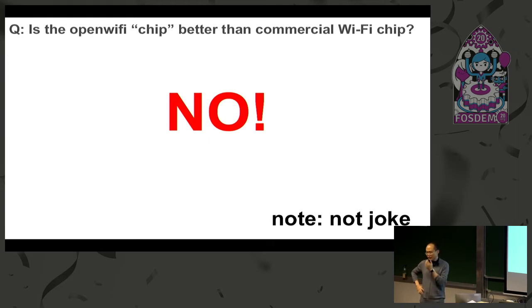Well, as you may know, those commercial Wi-Fi chips support quite new standards, right? AC, AX, and they support many antennas, right? Advanced MIMO processing, or high order MIMO. And they also support very high bandwidth. That means very high throughput, right? 20 megahertz, 40 megahertz, until 160 megahertz, right? Those chips are quite advanced. Unfortunately, our chip in this phase is not as advanced as theirs.